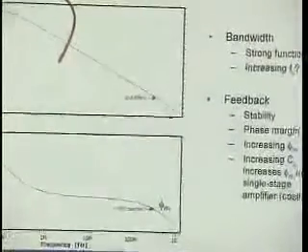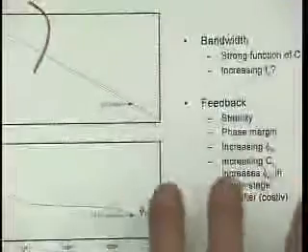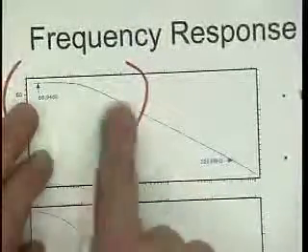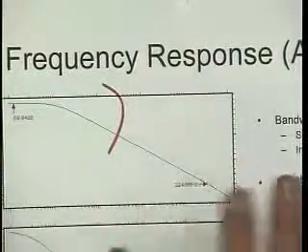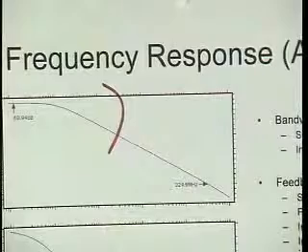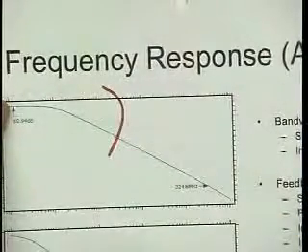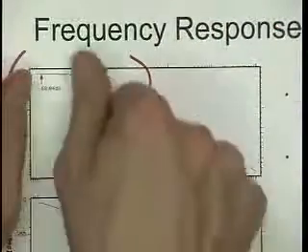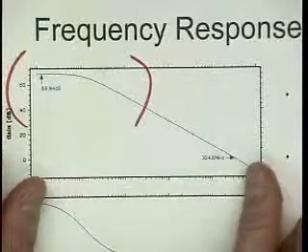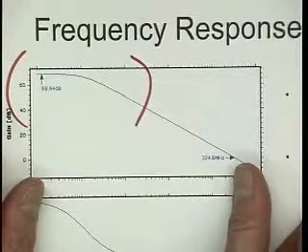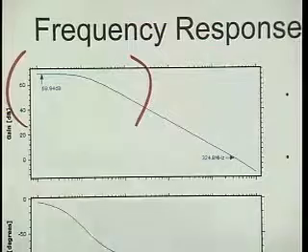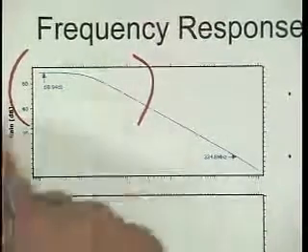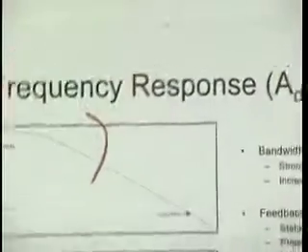Okay. Now this business, of course, sort of cries for feedback. Right? This amplifier here looks interesting, has a high gain and so on, but as is, it's almost useless. Right? We need to apply feedback so that we can get a bandwidth of not 100 kilohertz here, but a bandwidth of a few hundred megahertz, right? And a gain of maybe 2 or 4 or whatever that is precise and doesn't vary all over the place. Okay.